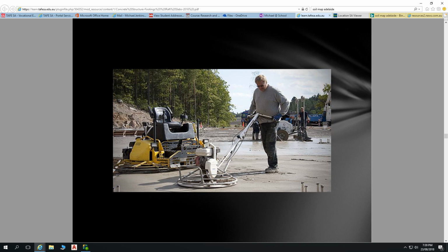This motorised trowel here, like the ride-on one, can get really good finishes on top of your concrete, because it can sit there just working all the aggregate down, flying across the top until you get these mirror finishes on your concrete. You can do the same with this. Essentially, it's going to take a really long time, because it takes a lot of working that concrete down to being perfect.